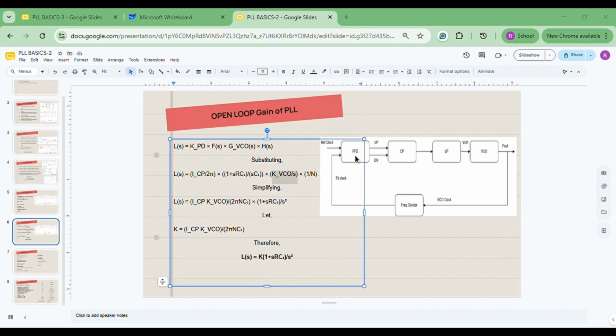Again, in outputs, we select on schematic. We have added this feedback clock here. Why we have added the feedback clock is because we are feeding from here, and we want the AC response of this output. After this, if you open, you can see loop gain and phase. All this we have added using stability analysis, which we will see just now.